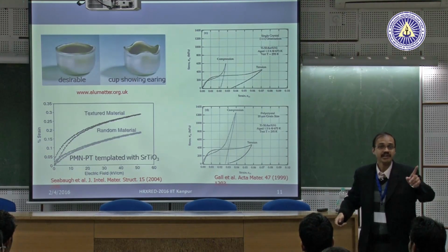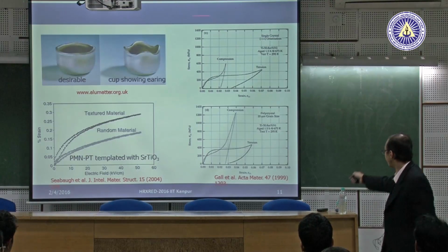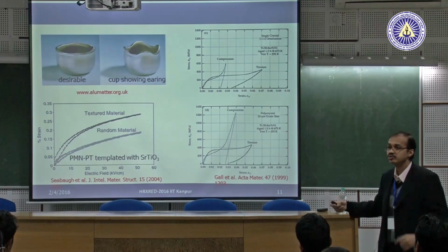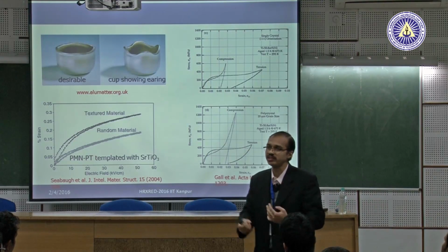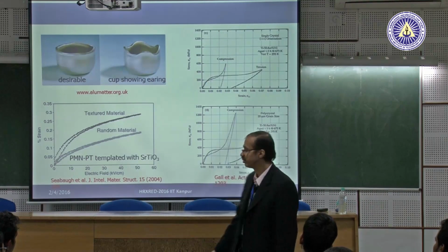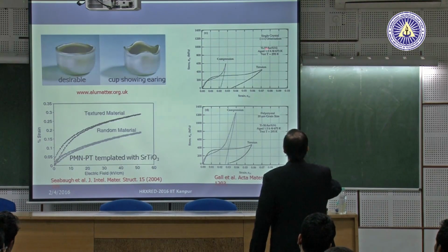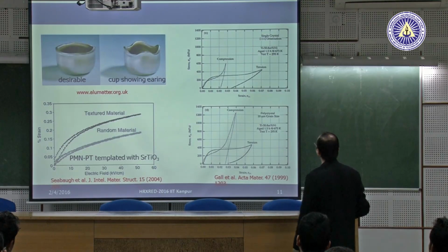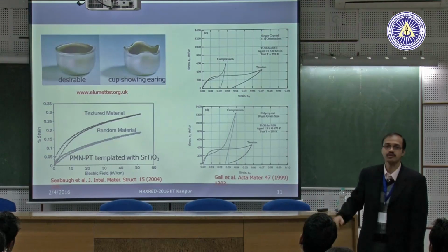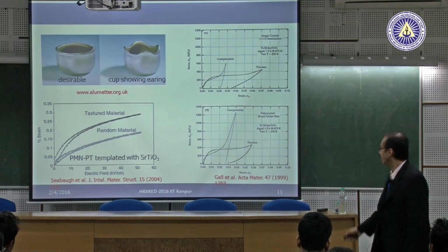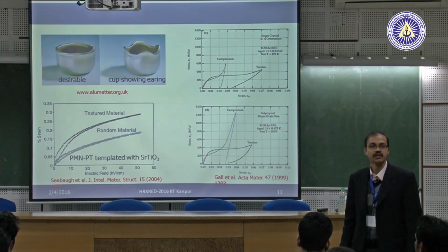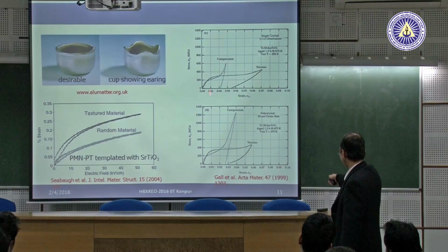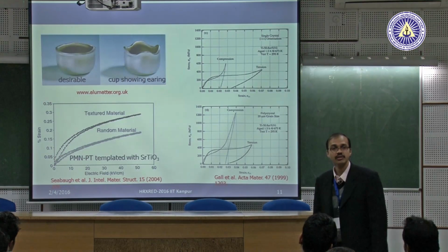Same material, mind you, the material is not changed. For 111, you are doing tension and compression, and it is so different. For the same cubic material, we say, bhaiya, you do a tensile test or compression test, you will get the same yield strength. Not so for this material, not so for nickel titanium. This is one material which Professor Ungar also talked about. Not only that, if you take a polycrystal, you see the same thing in a polycrystal. Similar anisotropy. In fact, anisotropy has increased.